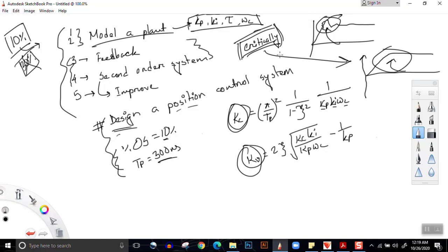So over time the performance will decay, but even then it will ultimately reach the critically damped position, and at a much later time it will reach the overdamped position. So the lift will operate at our desirable performance for a longer period of time. In general, whatever we design, we keep a scope for a little bit of overshoot, and we design an underdamped system. We do not design a critically damped system unless the problem statement specifically states it, or the stability is very, very important.